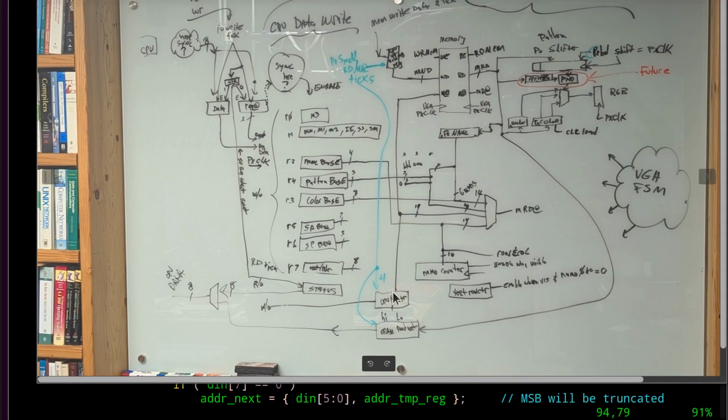And remember, that's this register that's sitting down here in this diagram. This goes into this mux, and this mux is used to say I want to read from the pattern table or the name table, the color table, or the sprite attribute, whatever. One of the inputs to this mux is the address counter, and that's all we care about right now. This is what governs our read address. So whenever I do a mode 0 read, I need to make sure that the address goes over here, bang, and gets the value out of this thing. And then when that's done, I need to advance this counter.